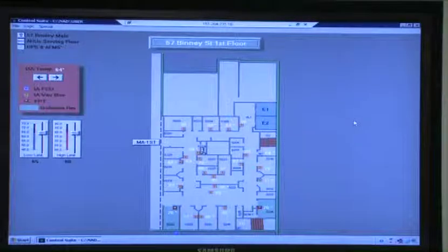Do you remember the issues we had about 6 West, 614, 600 constantly alarming because they leave the door open? All right? Well, we conquered that by putting in door contact closures. If the door is open, we will not get an alarm. If they close the door and it still doesn't have its right pressure relationship, then we'll get an alarm. So when you truly get an alarm, you understand that it is an alarm. When we're actually responding, it's because the door's closed and we lost pressure in the room, okay? That's no longer a nuisance phone call.